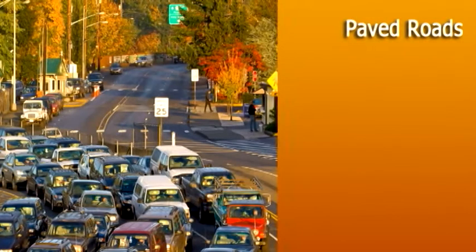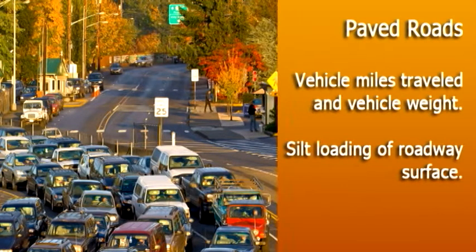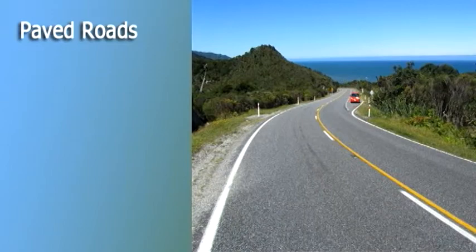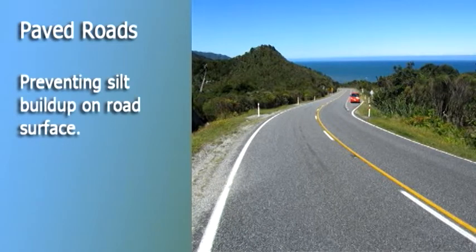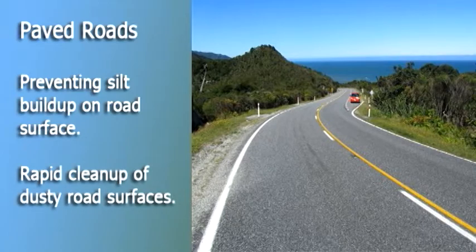Paved roads are a little different. The vehicle miles traveled and vehicle weight are important, and the silt loading on the road surface is important. Also, rainfall suppresses dust emissions from paved road surfaces and washes the roads clean on occasion. How do we reduce paved road surface emissions? By preventing silt buildup on road surfaces or by rapid cleanup of dusty road surfaces.